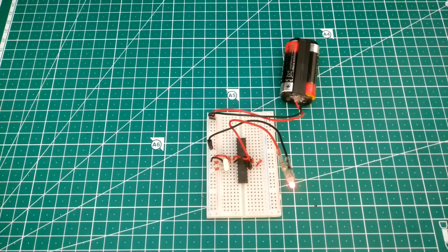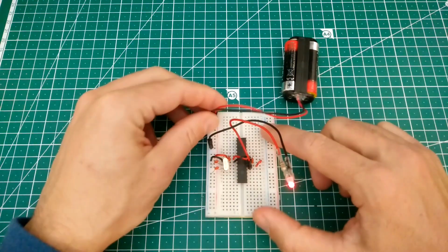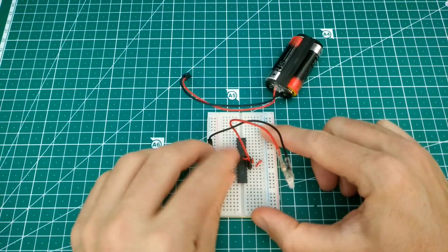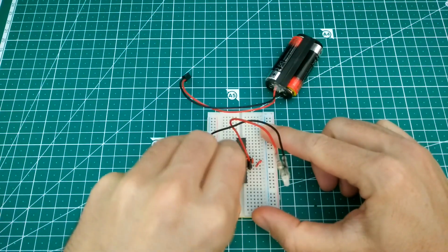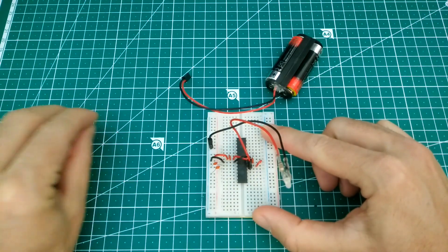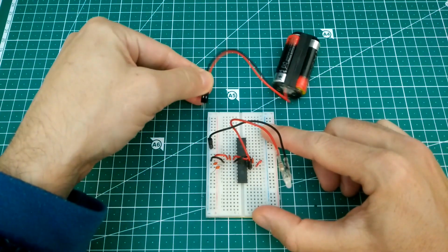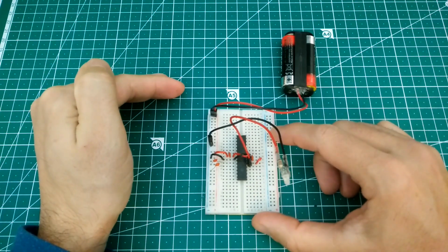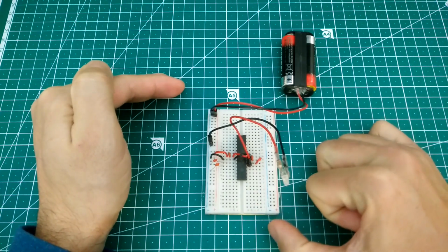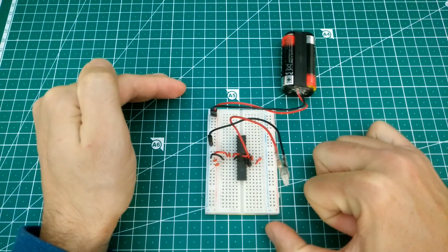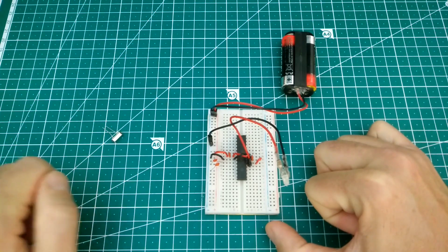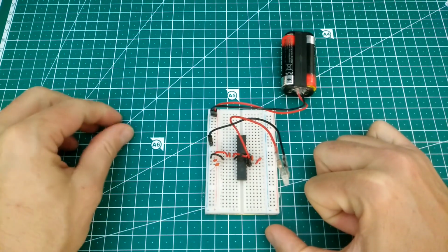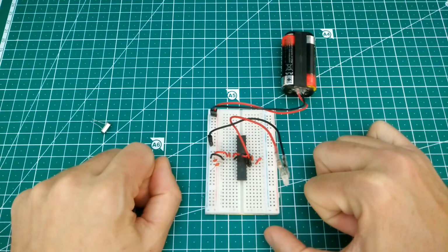Well, it's working, right? I'm going to show you, very easily, that it is actually the crystal working, not the internal oscillator. So take this off. Take the crystal off without taking anything further off, right? That's it. It's absolutely fine. And it's not working, which makes sense. There is no clock for this microcontroller. Some more modern ones might, but this one will not fall back into using the internal oscillator as default, so it doesn't run.